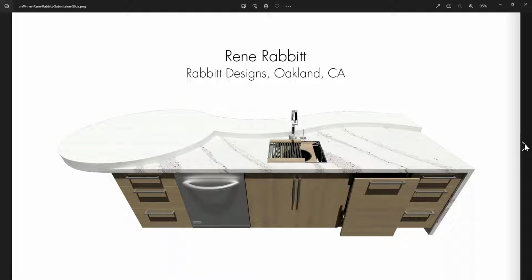So I did the CAD work on the countertop a lot differently than you did, kind of chiming in on using CAD reference lines. I drew out the 50 1/4 inch straight line, and then I drew 2 offset lines from there so that I could quickly reflect about object with a copy paste once I had the arc set in place. That was a big time saver, being able to get all 4 arcs done in, I don't know, 15 seconds or something like that.